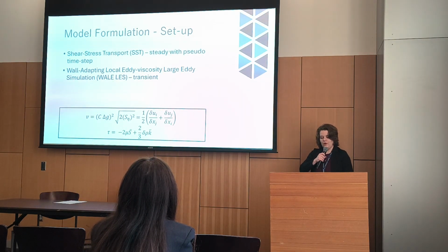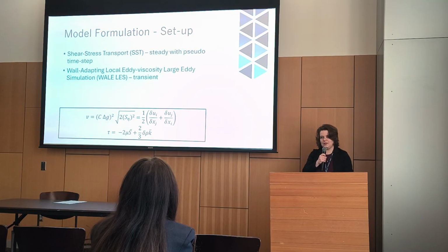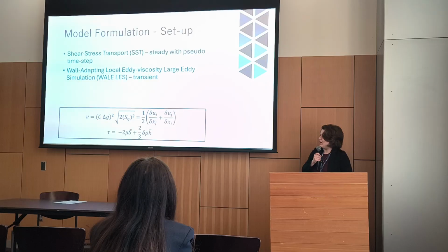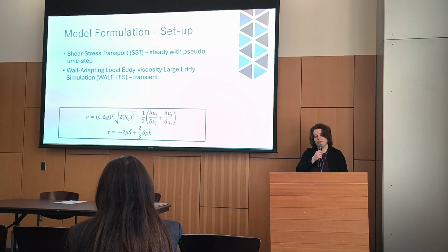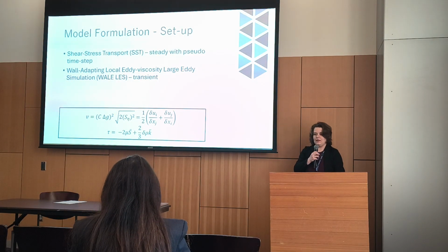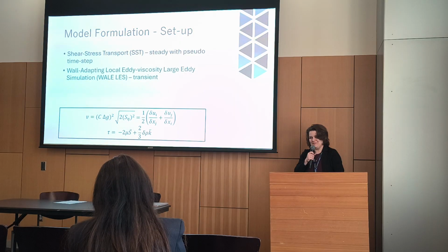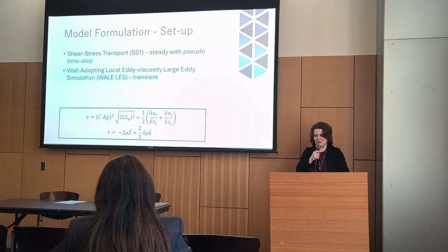Then we have wall-adapting local eddy viscosity, large eddy simulation. The wall-adapting model is specifically what we used for the LES. This is transient, and you can see that the first equation uses a different form for the same parameter, but the second equation is now with our shear stress. And this means that the mesh around our cylinder matters a lot, which is reflected.